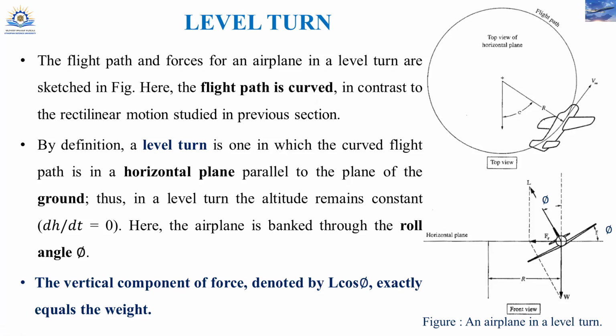So the vertical component of force for such a case is L cos phi, which is exactly equal to the weight. In this case, the weight is acting downward, and the lift component is L cos phi. Look, lift is in this direction.